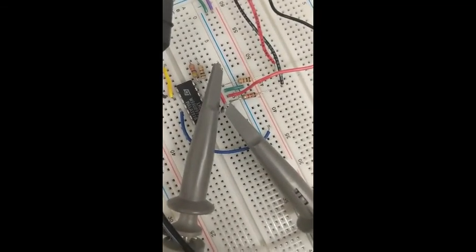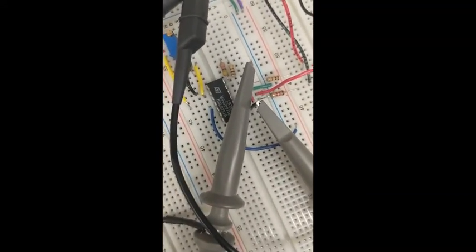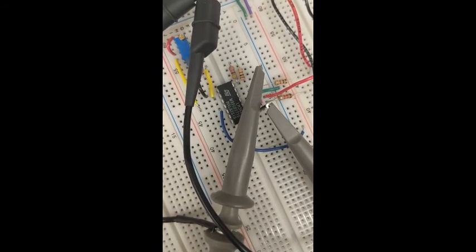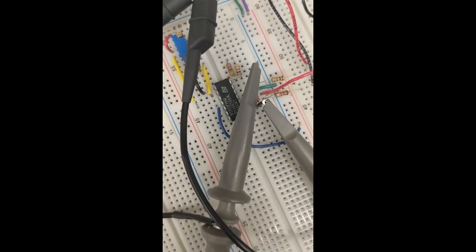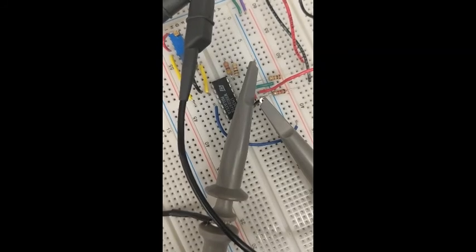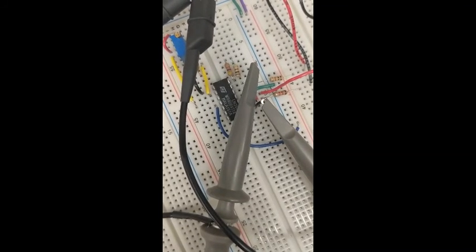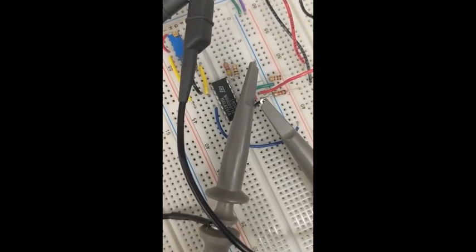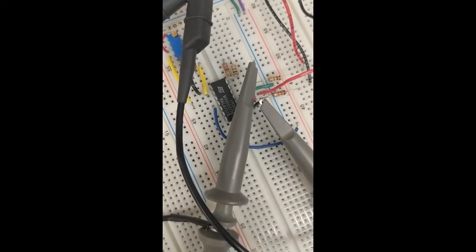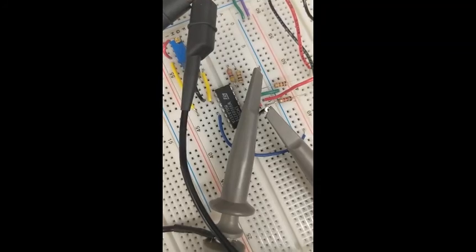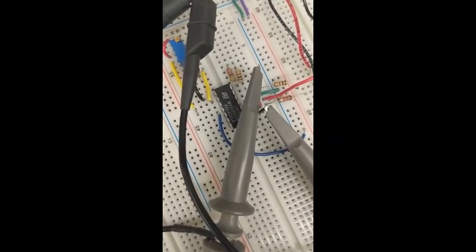This is our Schmitt trigger circuit. The Schmitt trigger circuit takes a signal and turns it into a digital signal with on and off. To switch from off to on, the signal must pass first through the low, then to the high threshold to turn on, and from the high to the low threshold to turn off. Our low and high threshold voltages are 3 volts and 7 volts respectively.